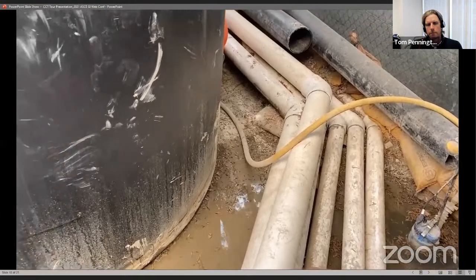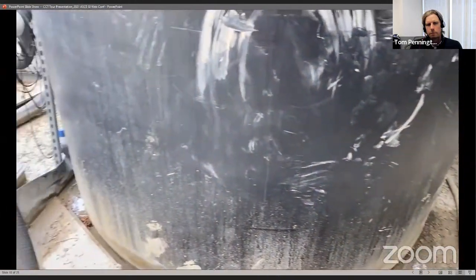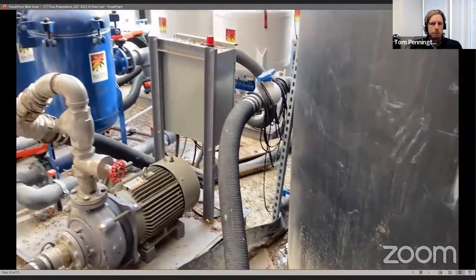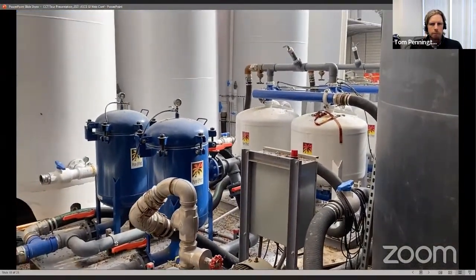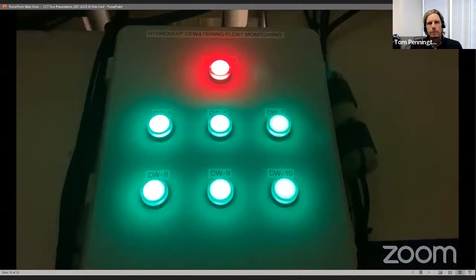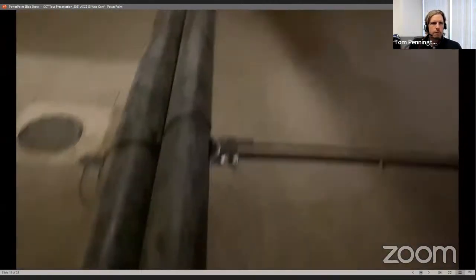Prior to the start of tunneling, the groundwater was lowered to a depth below the tunnel alignment by drilling a series of wells and pumping out the water. Groundwater is maintained below the tunnel during construction because water destabilizes soils when they are excavated.